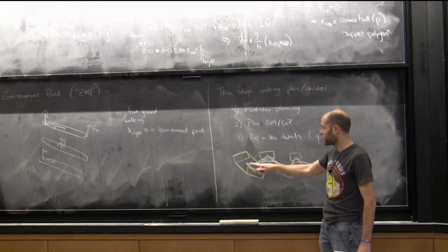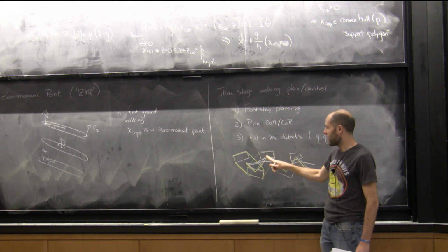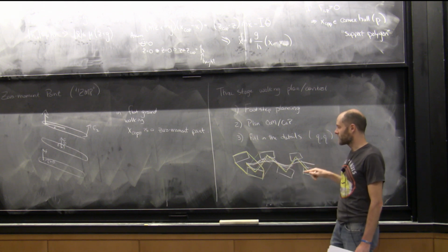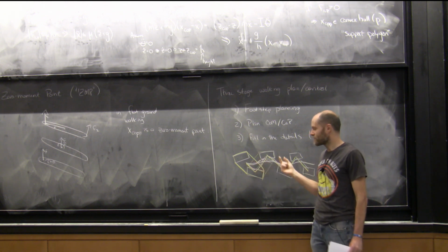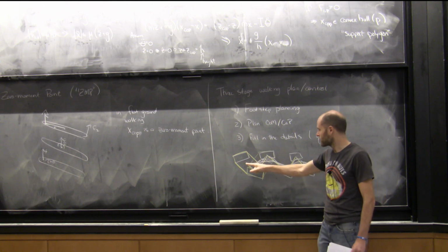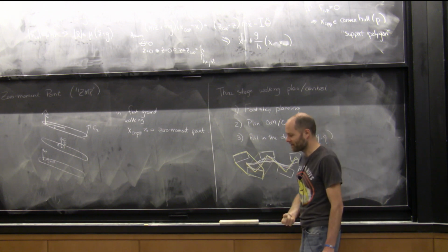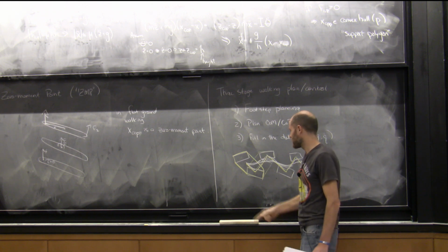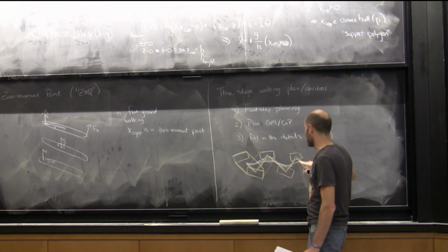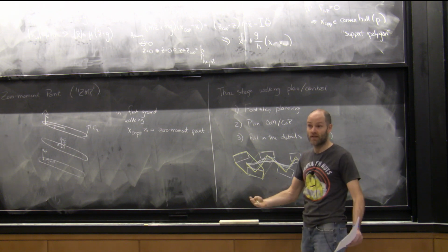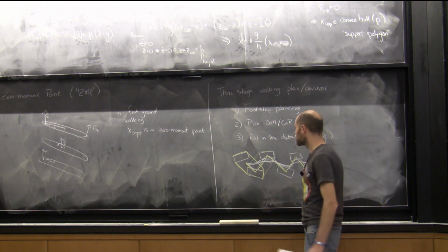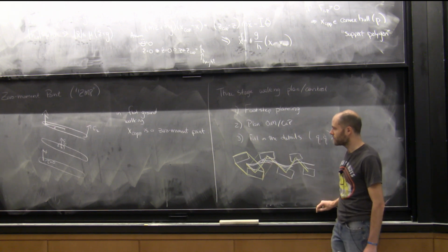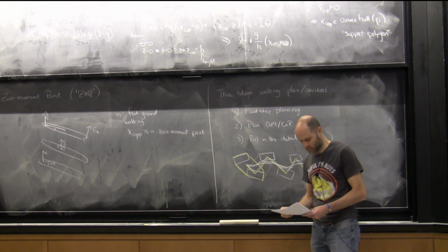So, for instance, you maybe have a desired center of pressure trajectory that looks like this, and a desired center of mass trajectory that looks like this, but you could say, find the center of mass trajectory that takes as little effort from my moving around as possible. I could deviate the center of mass as little as possible, subject to some quadratic cost on the deviation. Those kinds of things now are just a quadratic program. Okay? So that became a linear optimal control problem once the footstep plan is given.